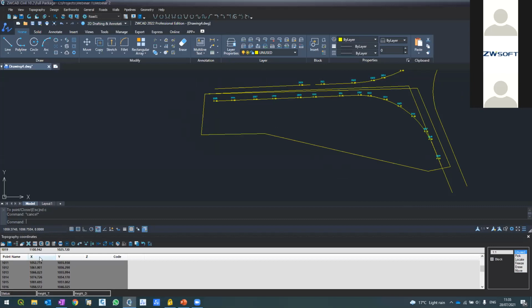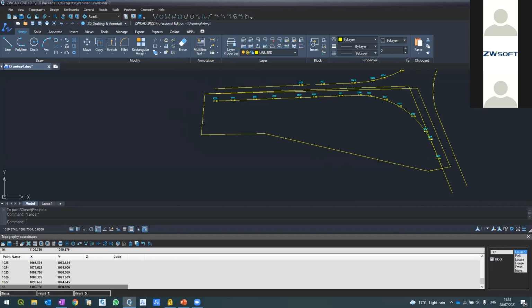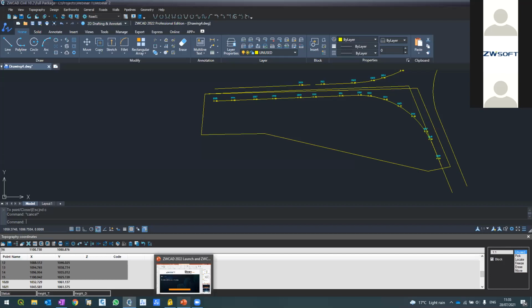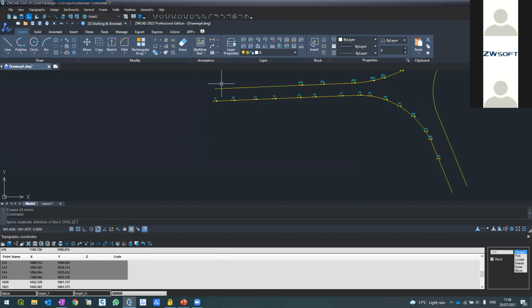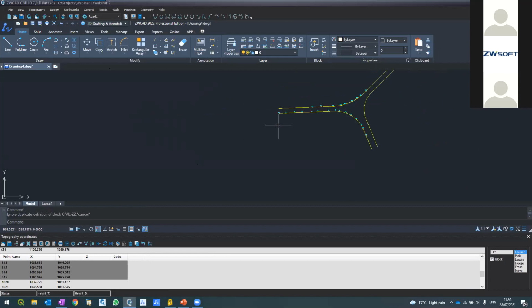You can see down here. I can now catch them as a block. I mark the block here and tell the software to renumber them starting from 1. So now all of them become 1, 2, 3, 4, 5, 6, and so on. And now I also want to give them not just a number, but a name. So this is the junction, south part of the junction. So I call it south, S. If I refresh, now all this will become S1, S2, S3, and S4.